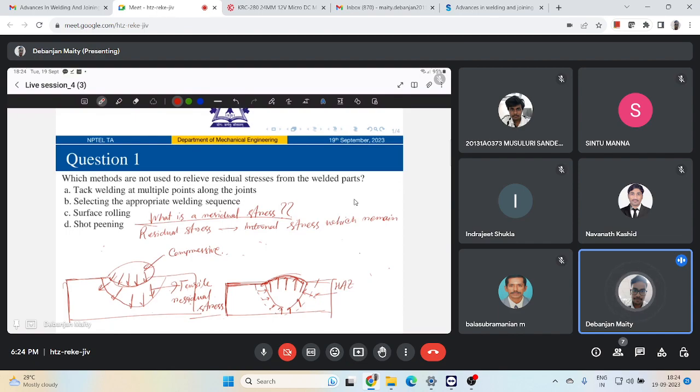Then there is something called neutron diffraction, where it can measure the residual stresses deep below the surface to a depth of something around 30 centimeter. So neutron diffraction is very much accurate to measure this residual stress to a higher level of depth in a surface.